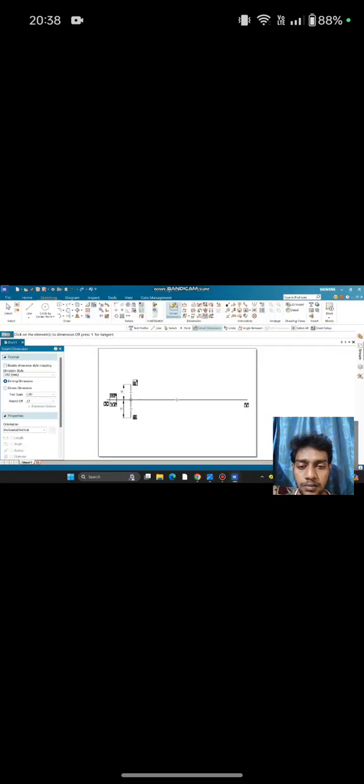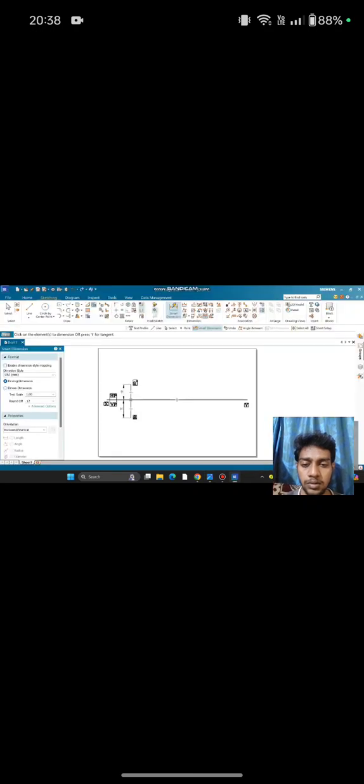Second point is nothing but point B. Point B is 35 mm above HP and 40 mm in front of VP. So now let's mark these points. 35 mm above HP is nothing but the upper part of the XY line, and 40 mm in front of VP is also the part of the XY line. Okay, this is VP. Above VP is nothing but this upper part.